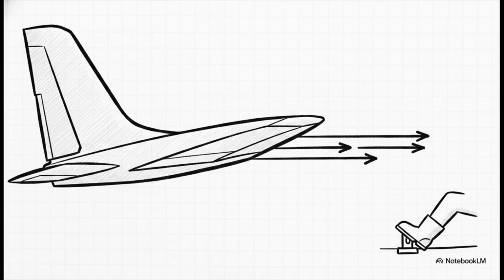Now, here is a super fascinating aerodynamic fact for you. The rudder doesn't just balance out the drag by creating more drag on the other side. Actually, no. The rudder acts like a vertical wing. It physically creates sideways lift to yaw the nose directly into the relative wind, actively countering the downward aileron's drag moment. You are quite literally manually overriding the physics glitch.